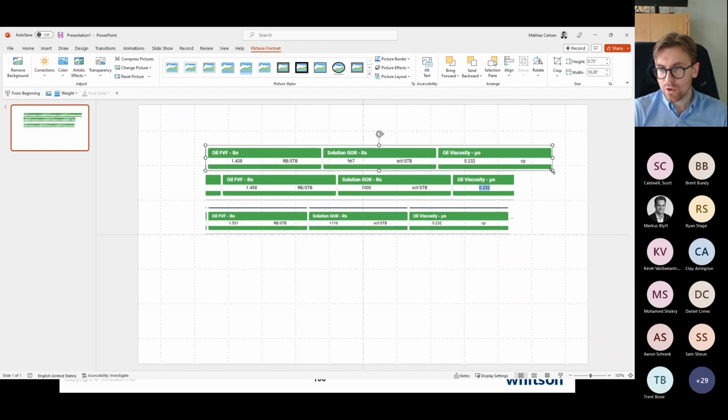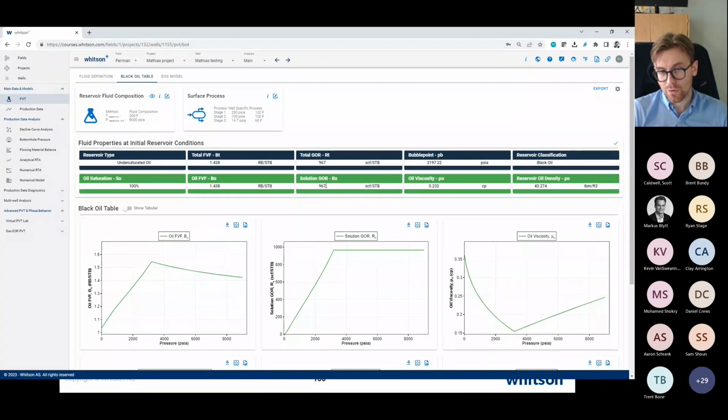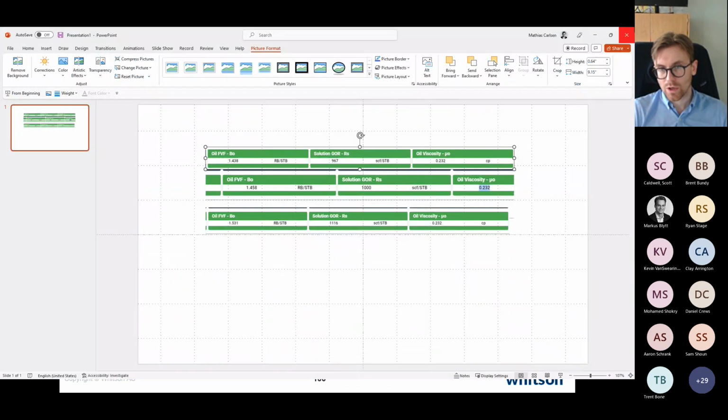Okay, so my point for you guys is that when it comes to PVT properties, these two right here, formation volume factor, and also if you're on the gas side, formation volume factor there and solution CGR, are a function of separator conditions. A leaner gas condensate is much more sensitive than a black oil to these changes. But you see there are still differences here depending on your process. So having a relationship to what your process is at surface is very important when it comes to PVT properties. Okay, doc?